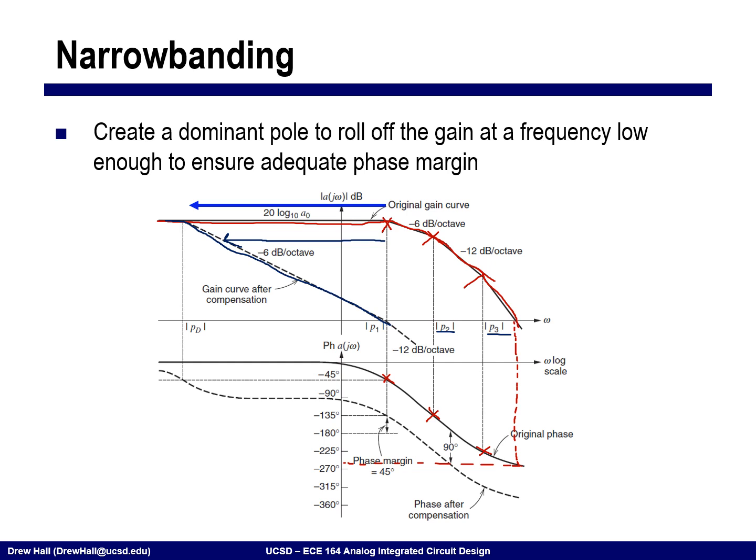And so what that does is that when we look at the phase margin here, you can see that we have considerably more phase margin versus this other case where we actually had negative phase margin. So this other original uncompensated case would be unstable. This case, we've stabilized the amplifier by adding load compensation. And so what do I mean by load compensation?